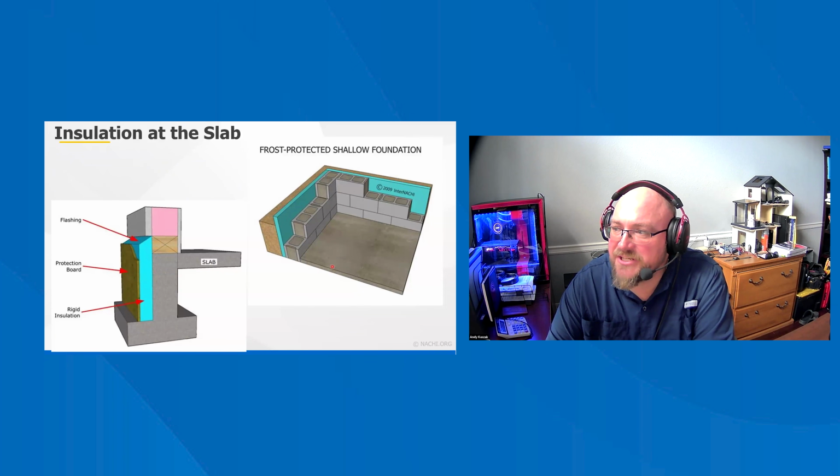If slab-on-grade insulation is placed in a different location, on the inside face of the perimeter foundation wall, then there should be a continuous thermal break between the indoor portions of the slab and the exterior. When used, exterior foundation insulation must be protected from the elements at additional expense. One way a builder could reduce costs while